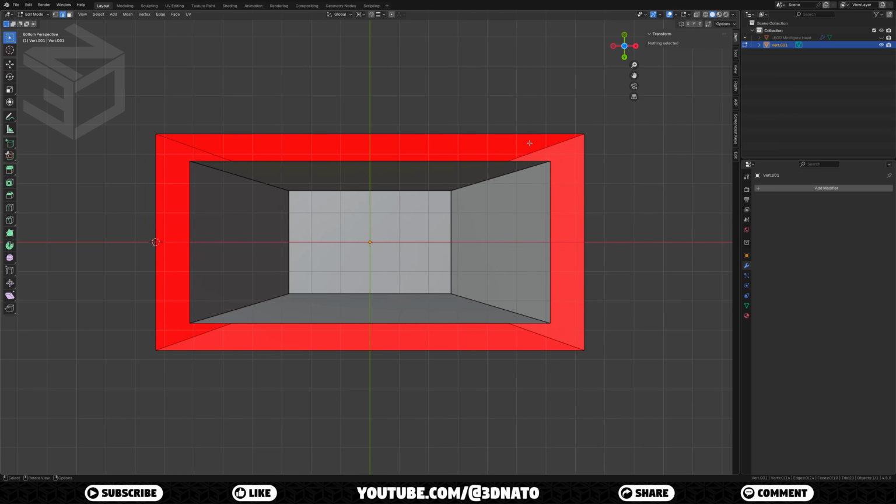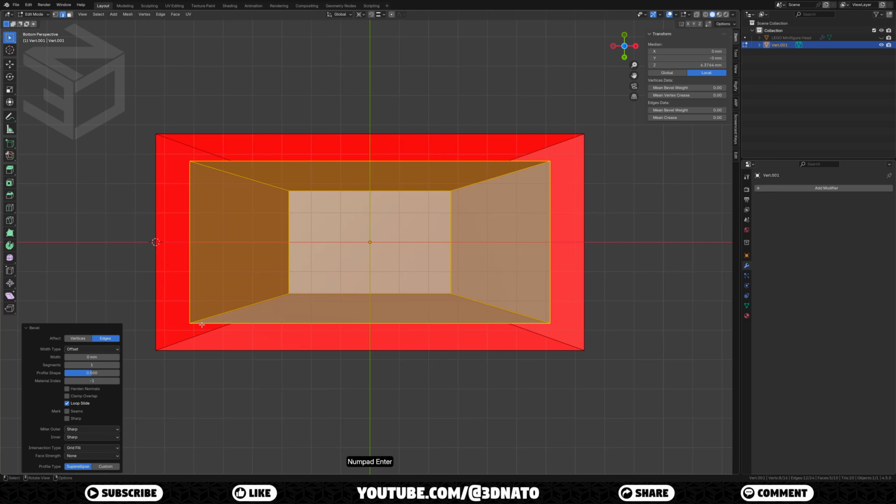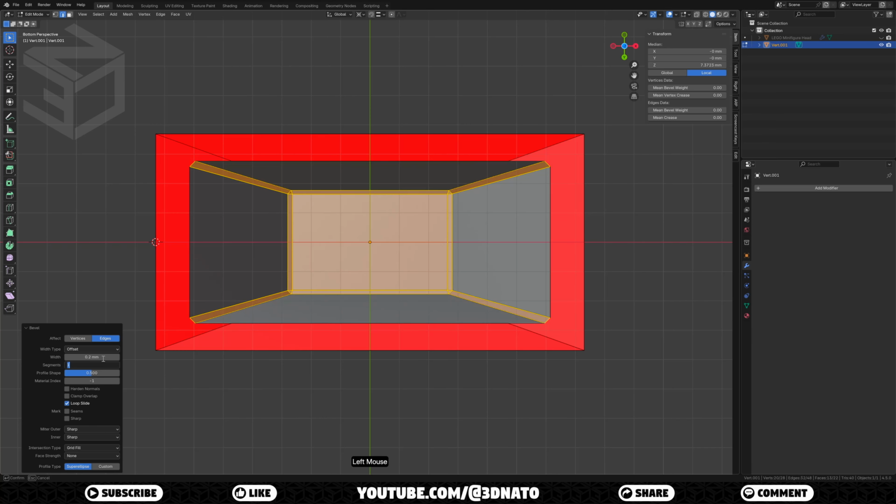For the outer shell, we'll need a 0.4 mm bevel, and for the inner shell, we'll need a 0.2 mm bevel. Let's start with the inner shell. Select all inner faces, press Ctrl+B to bevel, and enter to confirm. Set width to 0.2 mm and segments to 8.